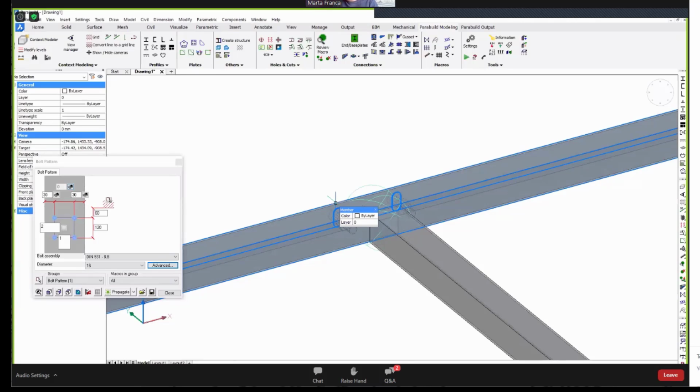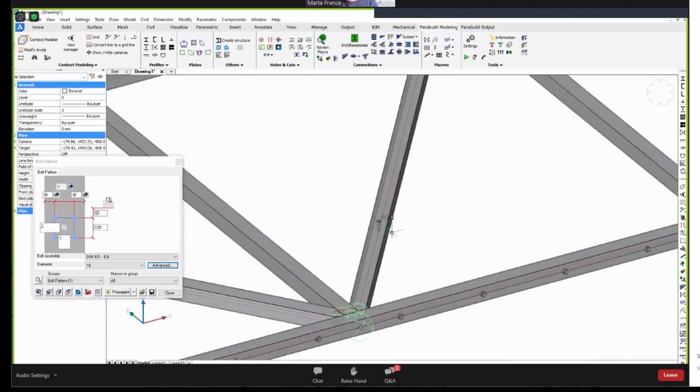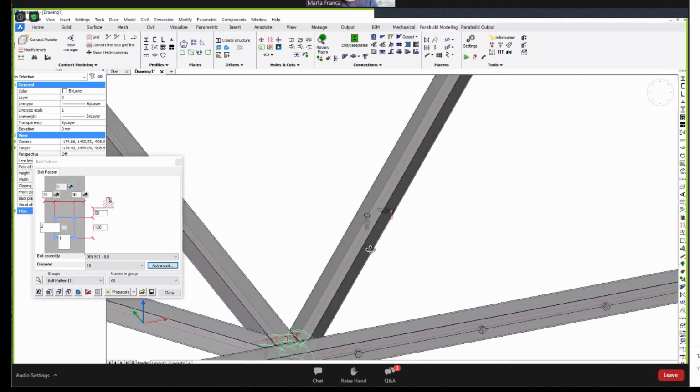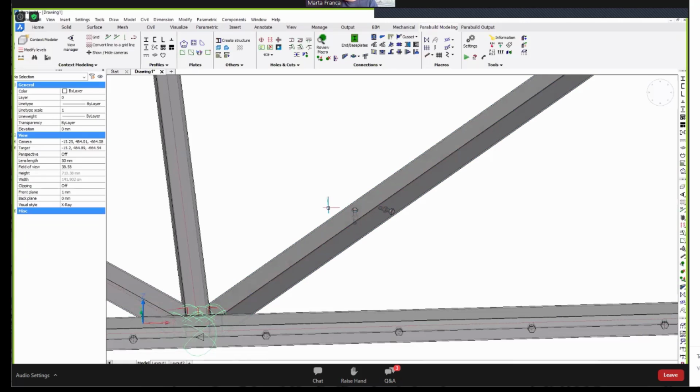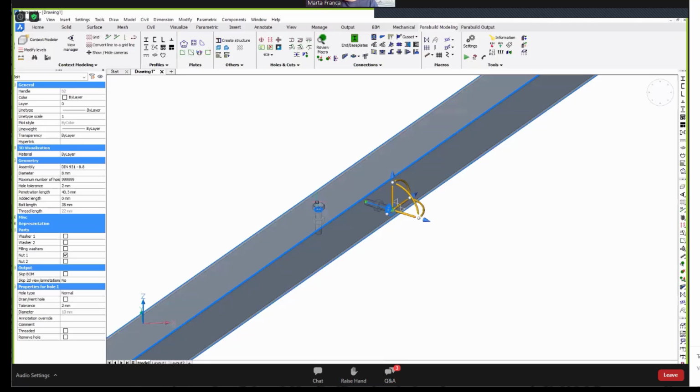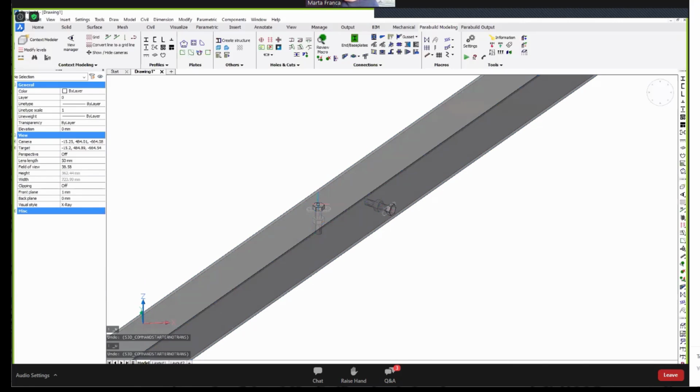So if I do it in a macro, then I am doing that for all of the bolts and holes in that macro. So that can speed up my work, I mean. But say in case that we do not have a macro, like here, these are single bolts drawn manually. So here, I could as well just activate slot holes, as you can see, or I can go back and I could activate threaded holes.